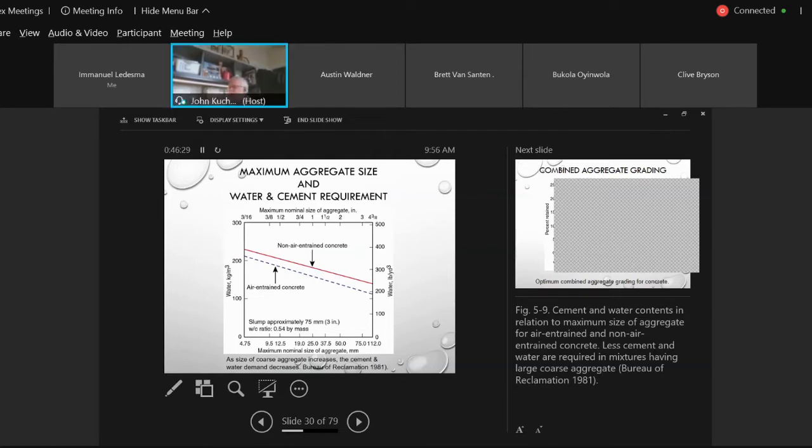Nobody did concrete testing? Would that be when they use like a vibrator to remove the air bubbles from inside the concrete? No, that's entrapped air or voids. You want to, yes, consolidate it. You can over consolidate it or over vibrate and knock out some of the air. But you've got concrete that has voids. Okay, and these voids are filled with the paste.